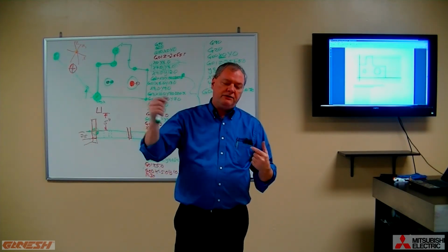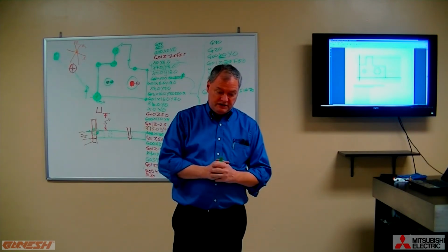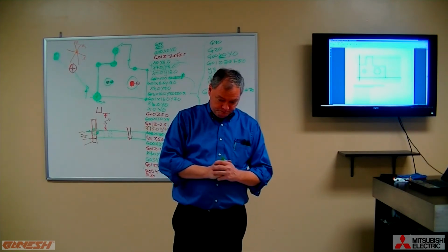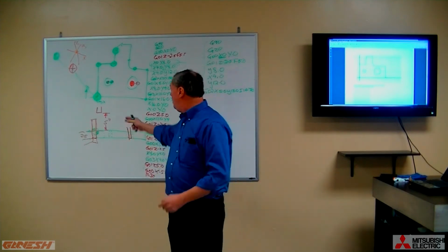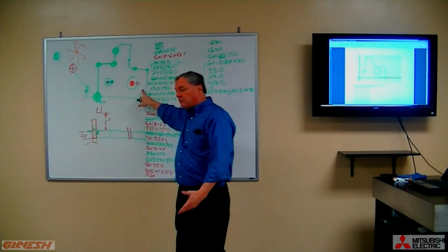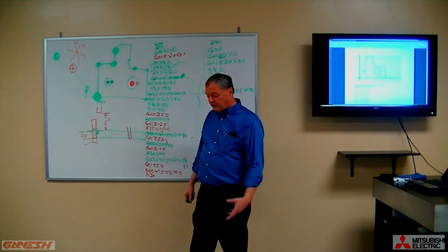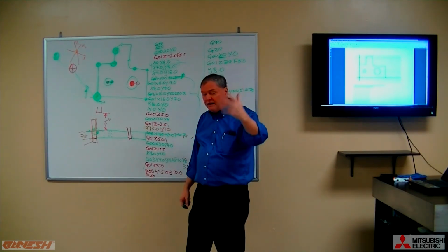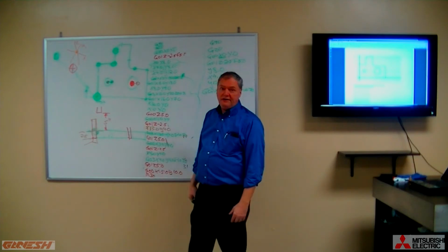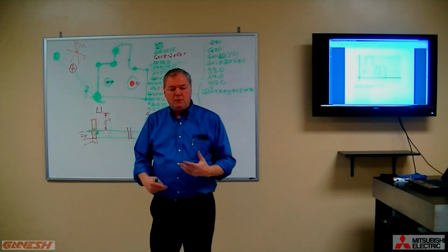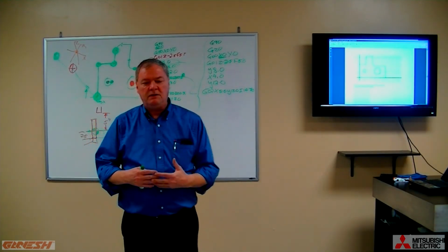And what is the appropriate RPM? Well, think back to our speed and feed discussion in machining processes. And you would need to know what material type this is. So if this were cold rolled steel, 1018 for example, you would have a spindle speed maybe 800, depending on your cutter diameter and so on. But the point is that you want to turn on the spindle.